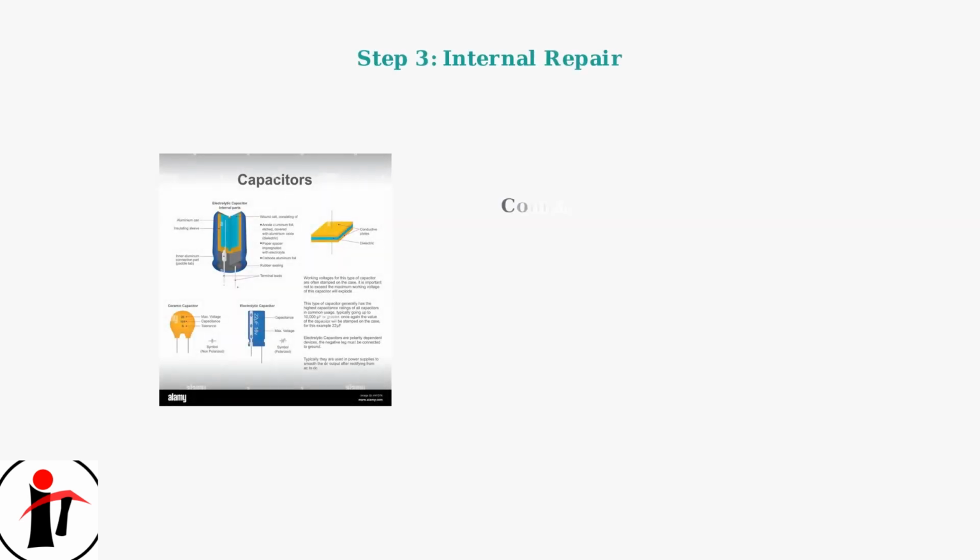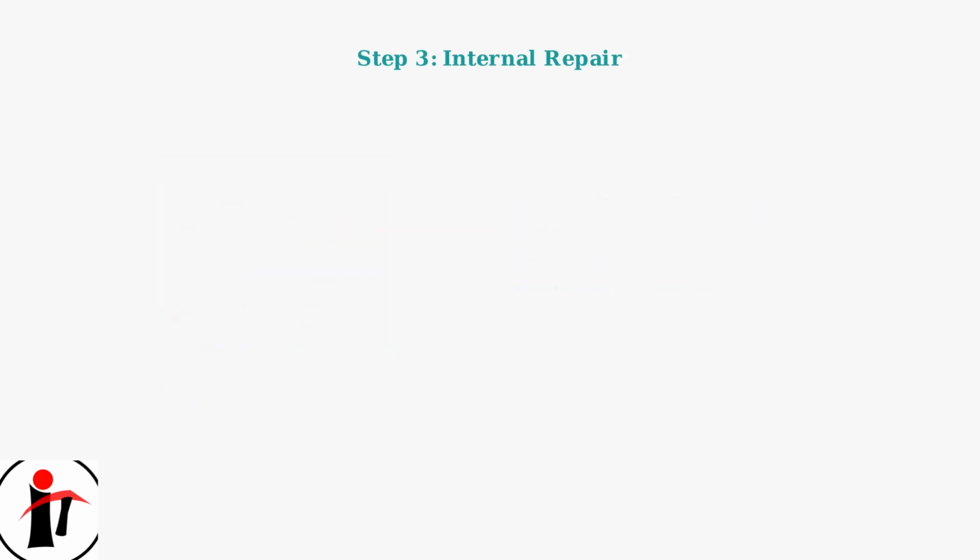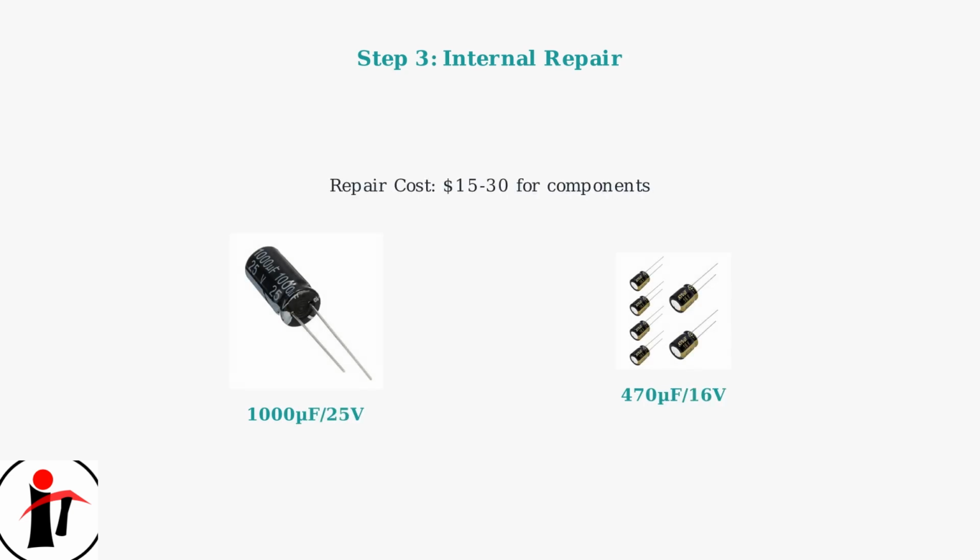If external troubleshooting fails, the issue is likely internal. The most common cause is failed electrolytic capacitors in the power supply unit. These components degrade over time and cause restart loops. Here are the specific capacitors that commonly fail.